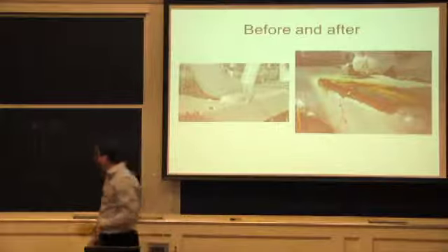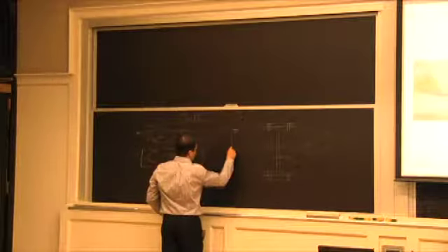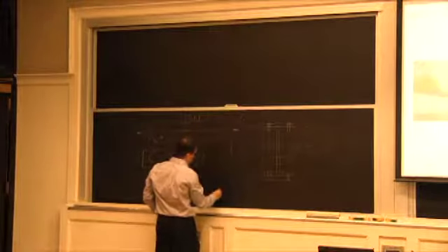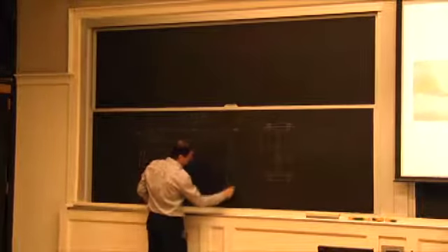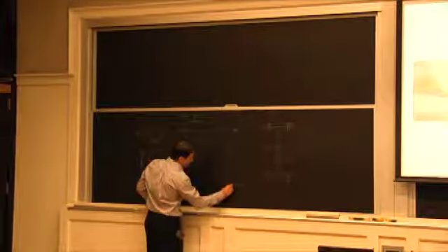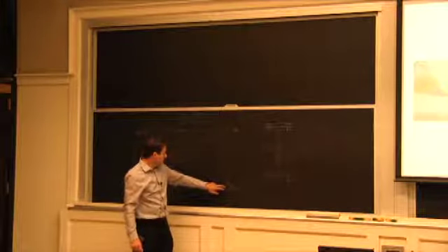So instead of having a fillet weld that's really just like this, and you make a nice bead, now you have to deal with it's on a round. So you have this empty root, and you're just trying to somehow deposit something in there. It's a lot harder weld to make than just at a corner.